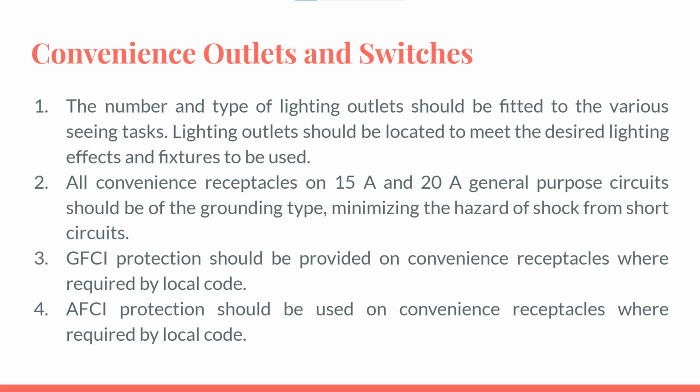Third, GFCI, or ground fault circuit interrupter, protection should be provided on convenience receptacles where required by local code. Example, where the occupant is exposed to water. Fourth, AFCI, or arc fault circuit interrupter, or arc fault detection device protection should be used on convenience receptacles where required by local code. Example, in bedroom circuits.